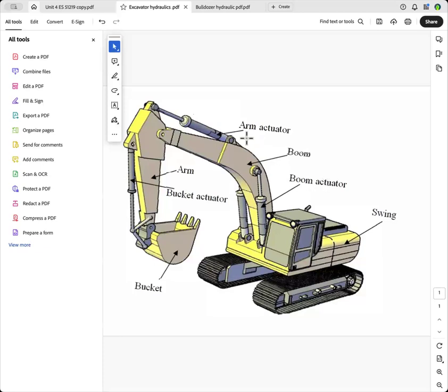And so this hydraulic cylinder up here, look at the way it's been arranged. It's been arranged so that the strong direction is pushing it out so that the bucket can actually dig into the ground. This one here, the strong direction is going downwards so that it can lift the mass of dirt or whatever that's in the bucket.